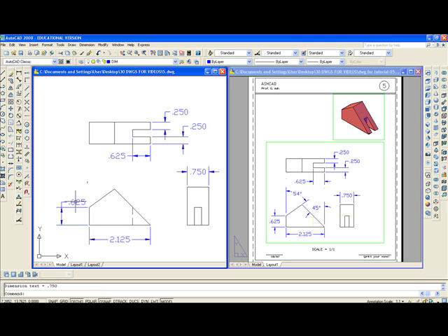You will remember that if I want to fix that, I'll have to take off Object Snap, take off Ortho, click on it, use the grips to move it down like that. Now then, in order for you to create an angular dimension, you need two lines. So I'm going to draw a line with the O-snap on, Ortho on, from this point up here like that. I'll also draw another line, hit the spacebar again, up here like this.